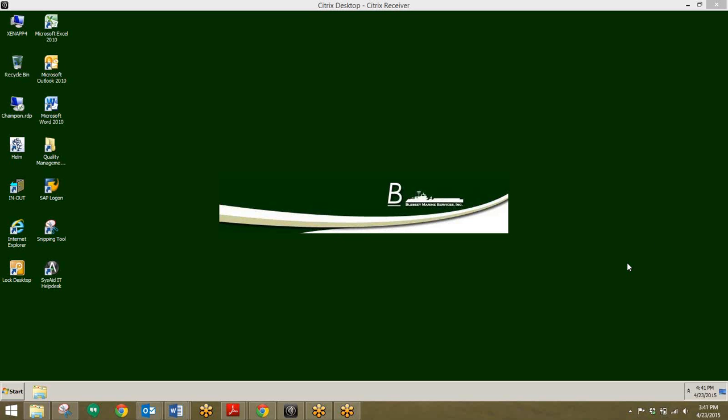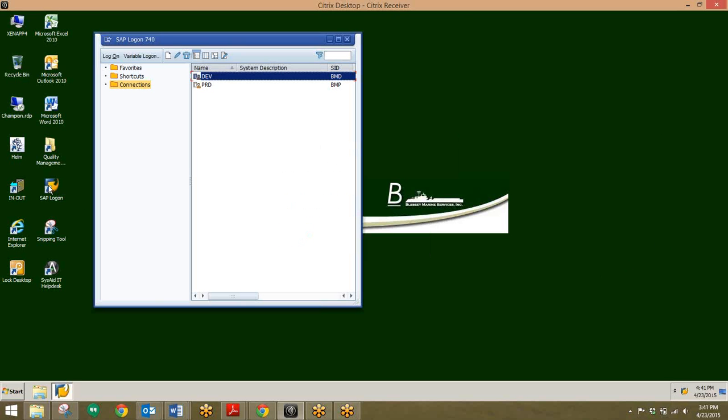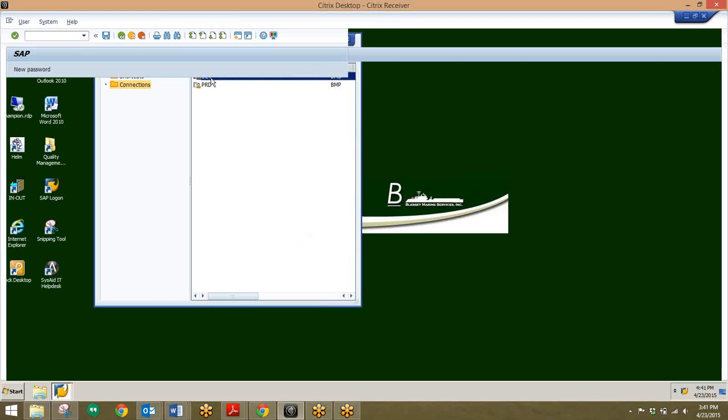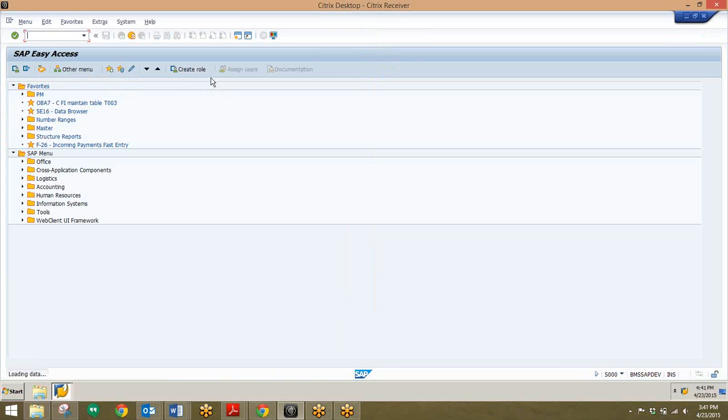So this first step will begin on page 6, but to start we'll log on to the system by clicking on the SAP icon here and entering in our user ID and password. And once again, this will be in the dev environment. Okay, so on page 6 is where we'll be starting here, and we'll be going over how to display plant maintenance orders. And the transaction for this will be IW39, so we'll enter that in the command box here.